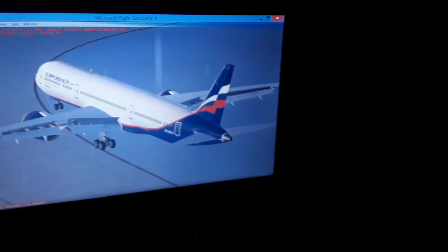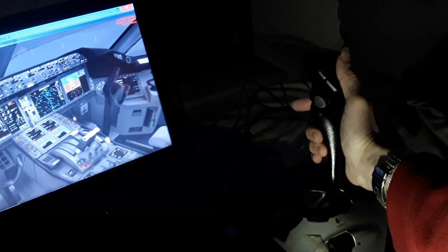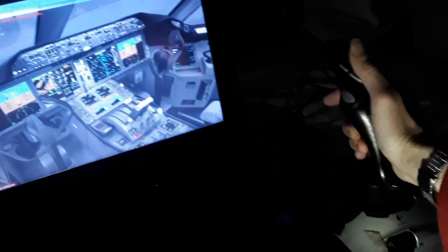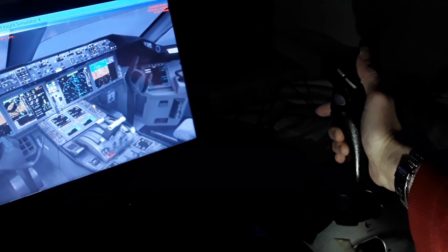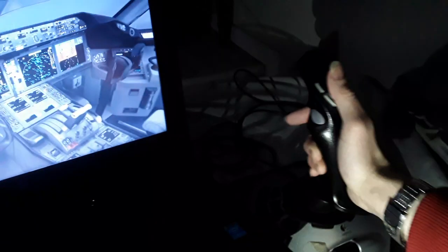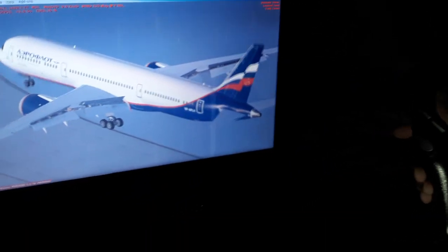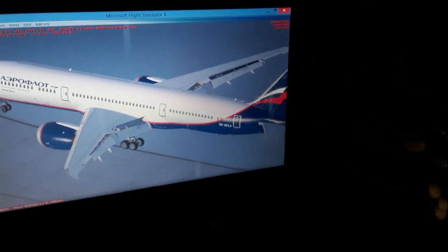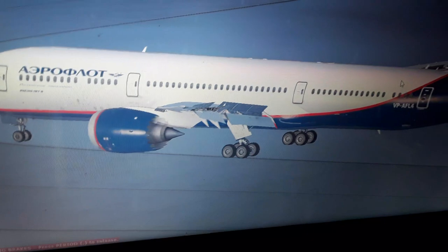So in the Boeing, you have the control wheel instead of the side stick, so you use the control wheel to make left and right turns, which is the roll axis of the aircraft. So this is all longitudinal axis of control and stability of the aircraft as it flies. You can see the side stick deflection is proportional to the yoke deflection. Also, I forgot to mention from the aerodynamics and the Bernoulli theory of fluids over here. You can see the bottom surface of the wings is more flat.